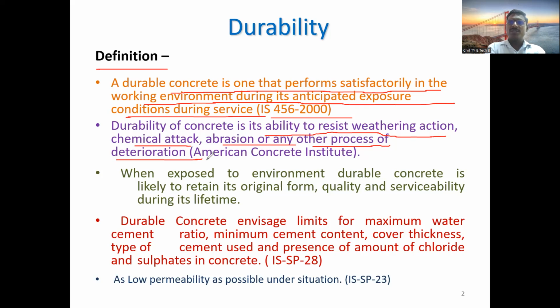So many more properties of the fresh concrete are there that we have to think about while making the concrete. Durability. Concrete strength: if you add a lot of water, more than the requirement, until the mixture forms, that is fine. But if you are using more and more water, automatically your workability increases and strength will decrease. If the strength decreases, the durability also decreases.